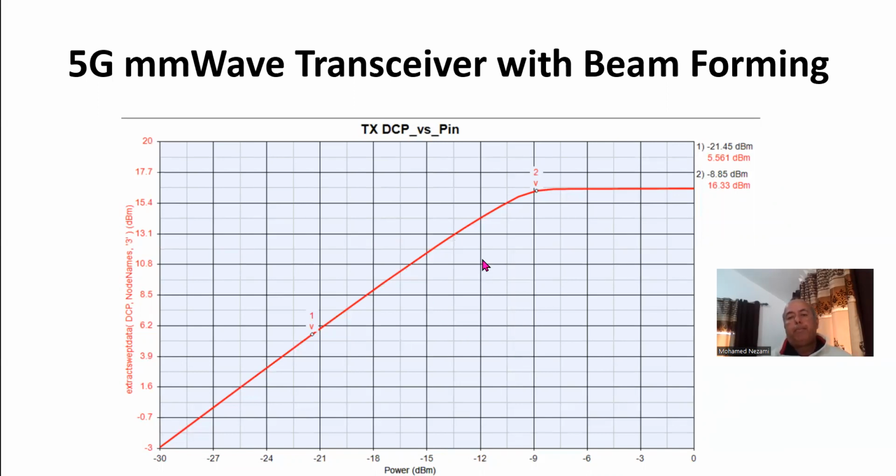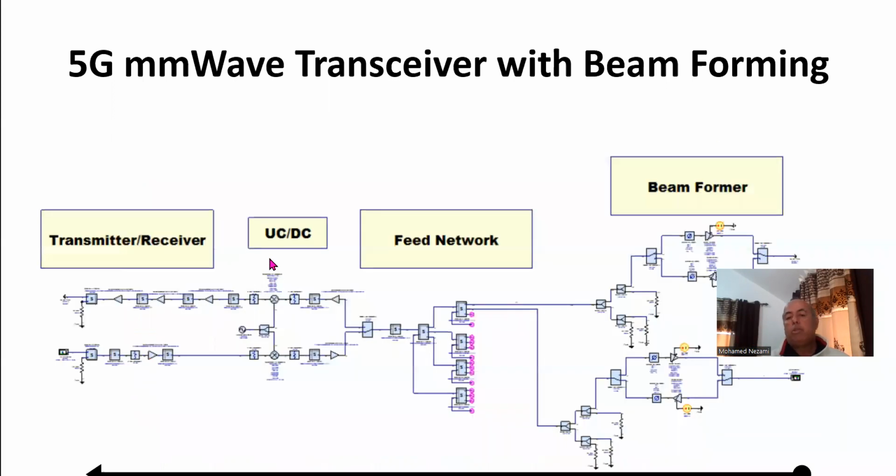Because the beamformer chip has a limitation on the output power level, if you need to go beyond that, you really need an external front-end section, which comes in as a PA on one leg and an LNA on another leg and 2 transmit receive switches. And that, of course, makes it more expensive. That would give a lot of EIRP, but we're not targeting that. We're targeting 50 dBm EIRP, where 21 dB is coming from the antennas, and the rest is 13 dBm from the beamformer, which is just sufficient.